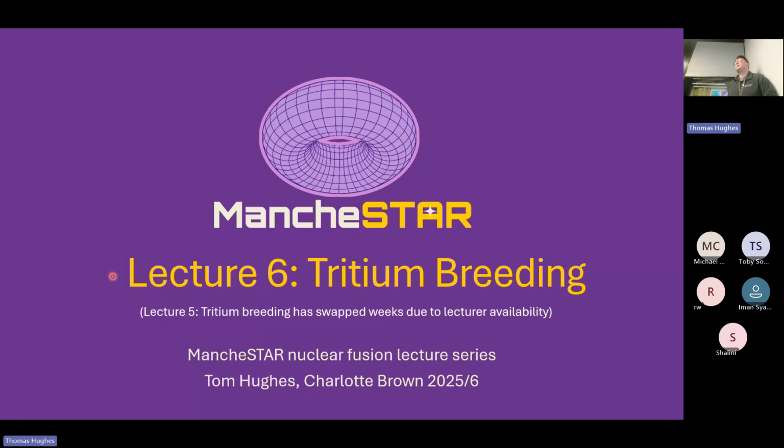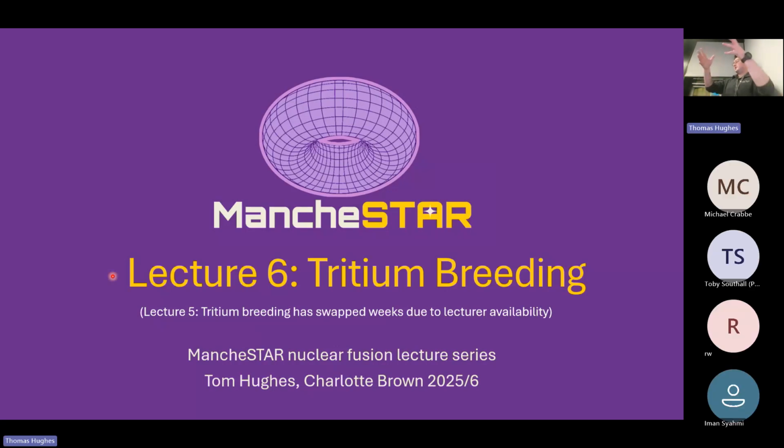The main ones that you want to be aware of are BCC, body centered cubic, and FCC, face centered cubic. BCC is a cube of atoms with one in the middle because it's in the body. Face centered cubic is the opposite way around, where you've got atoms on all the faces and nothing in the middle. HCP is more of a tetragonal shape. The easiest way to think about that one is if you have a line of spheres, and then you add on top another line of spheres offset slightly so they sit in, and then a third one on top, and that's your HCP.